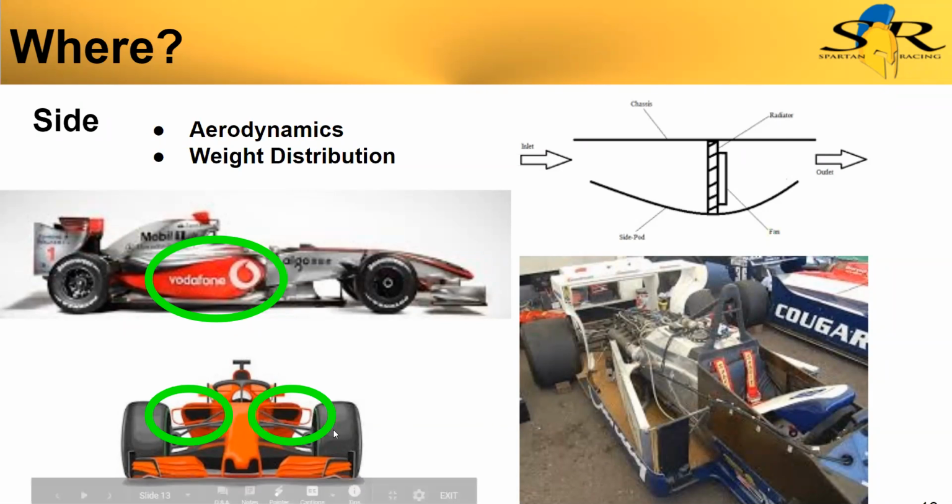A lot of the designs will have the side pod openings or the duct openings for the radiators really close to the side of the car to catch some of that air that's following along the body, and also to minimize the width of the side pod and minimize drag. So all of that has to be decided on and factored in when you're doing your overall aero package design and making those decisions.